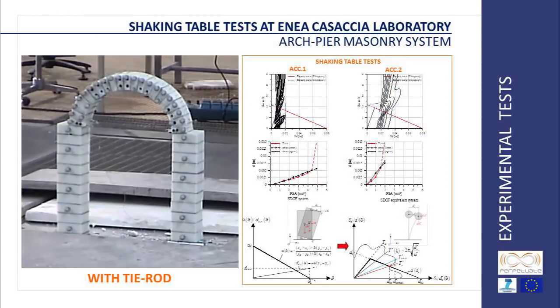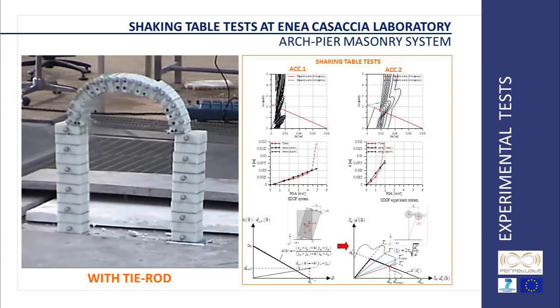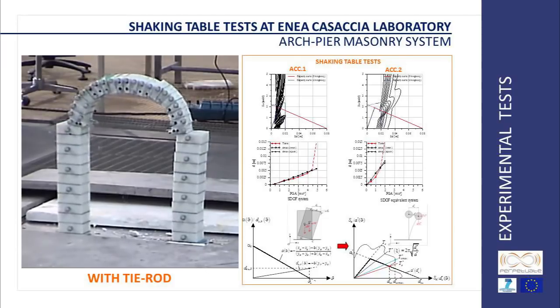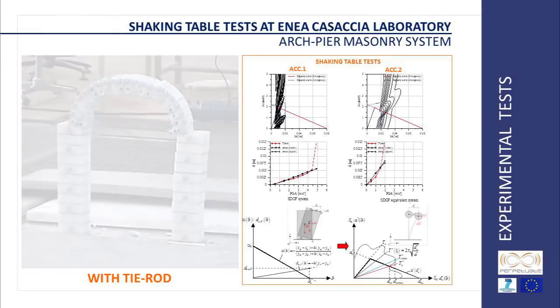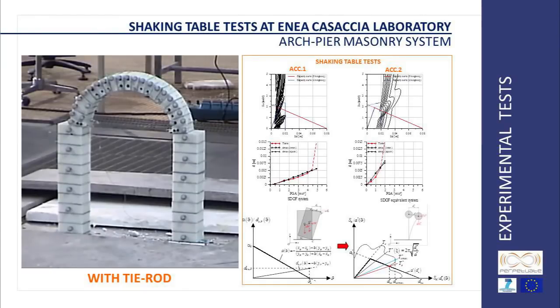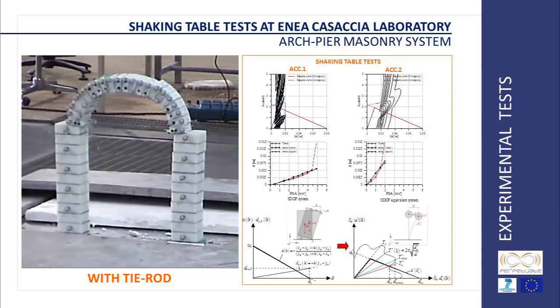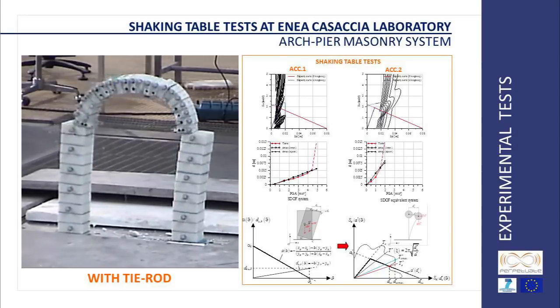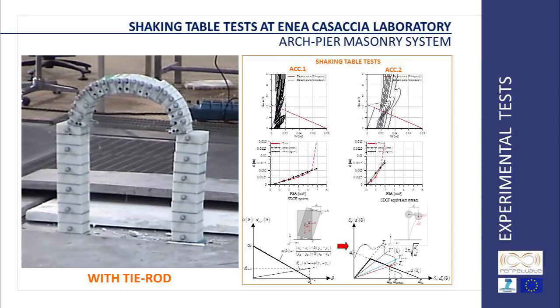Tie rods have increased meaningfully the load-bearing capacity of the system. The increase of displacement capacity provided by more deformable tie rods has also been demonstrated. Finally, the tests have been very useful to validate the theoretical models proposed within the PERPETUATE procedure.